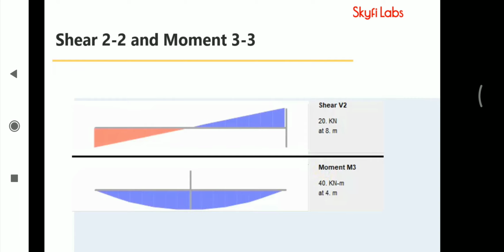For example, as mentioned before, shear V2 is a shear force in the 1-2 plane, meaning shear force on the plane between axis 1 and 2, that is, on the xz plane. Same is the case with moment M3, which is the moment in the 1-2 plane.